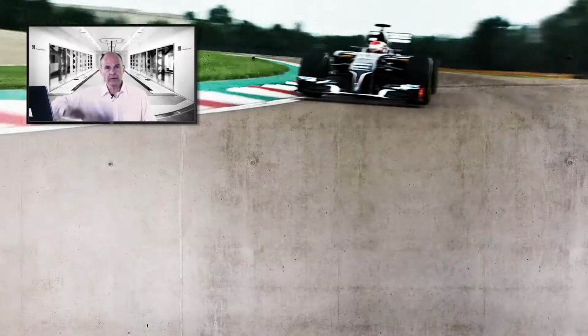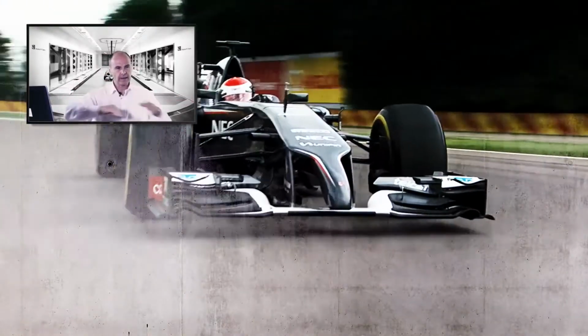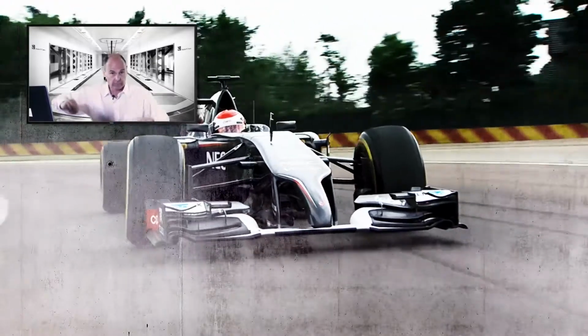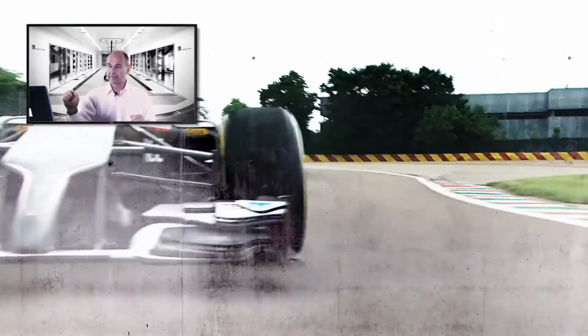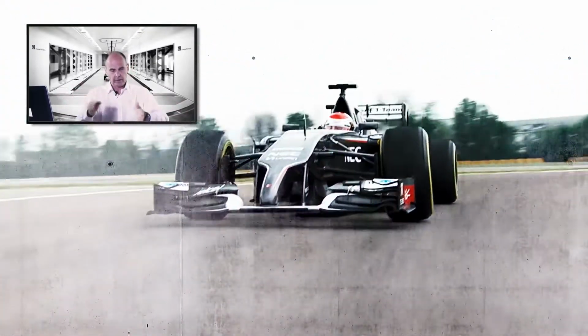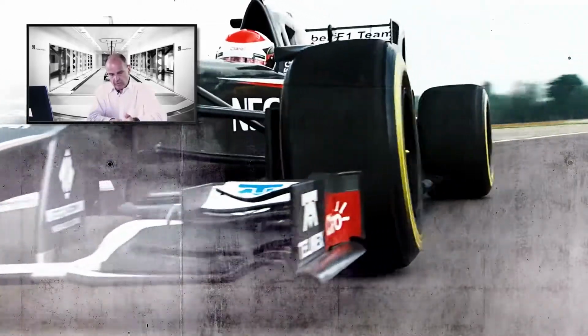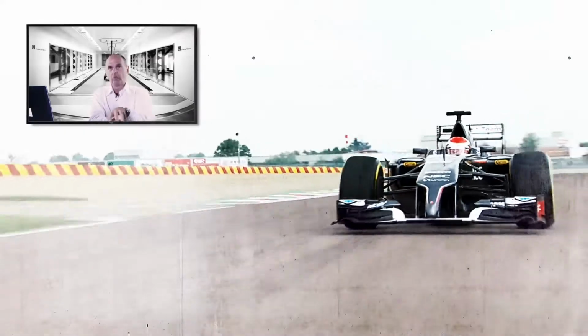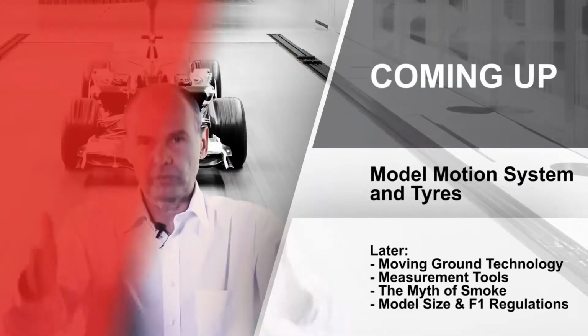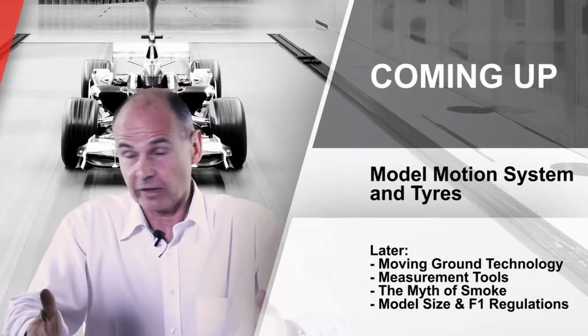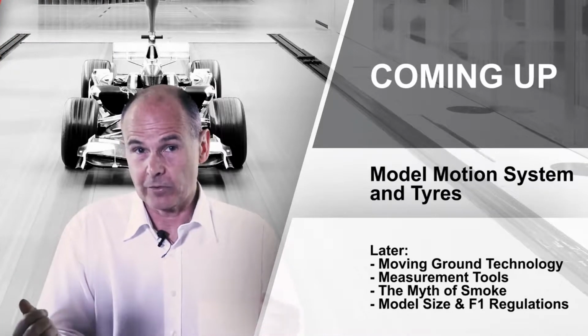So in reality, a vehicle will pass through the air and punch the air out of the way as it does. And in a closed jet wind tunnel, you have a restriction, so the air passing over the vehicle is sped up a little bit more than it would be in reality. If you convert to a three-quarter open jet wind tunnel, you don't have that problem anymore. You have some other challenges.